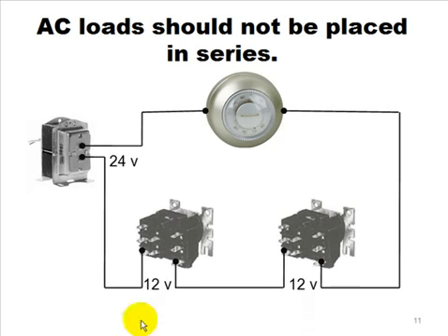This is what happens when you put loads in series. Go ahead and put light bulbs in series. No big deal. You can put switches in series because they're not loads, but you can't put loads in series, especially in AC circuits. You just reduce the voltage to each of the loads. If I put a third one of these in series, I'd end up with 1/3 of 24 going to each of them. Each would have 8 volts then. They would hum a little less and you get more smoke out of everything.